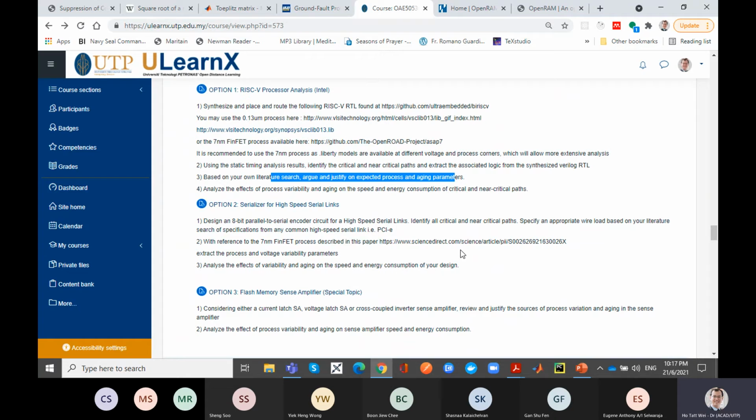How to answer that question? Then you start asking. Oh, process variation. Really, I'm looking for the smallest transistor, right? Minimum size transistors are a bit of a problem, because I have line edge roughness, I have dopant variation, or maybe I happen to be using a low threshold voltage one. Threshold voltage I know is also a very problematic one.